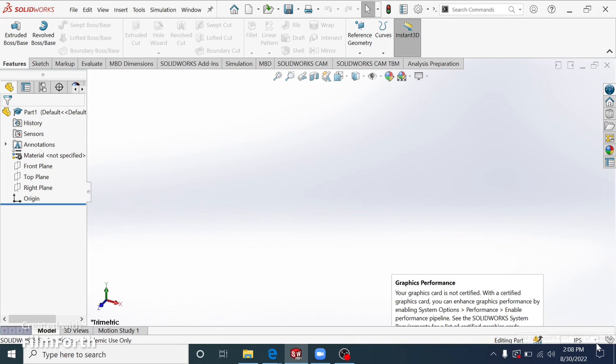The last one is this right here, your units. So you have these other functions. From the previous one, if you want to do your new, you have to change your units before that. It depends on what you downloaded. Or you just go down here to your bottom right corner, and it'll give you these units right here. You have the meter, kilograms, centimeters, millimeters, inches. So you have the English and metric system. Or you can actually edit the document units depending on what you're using. It depends on your site as well.